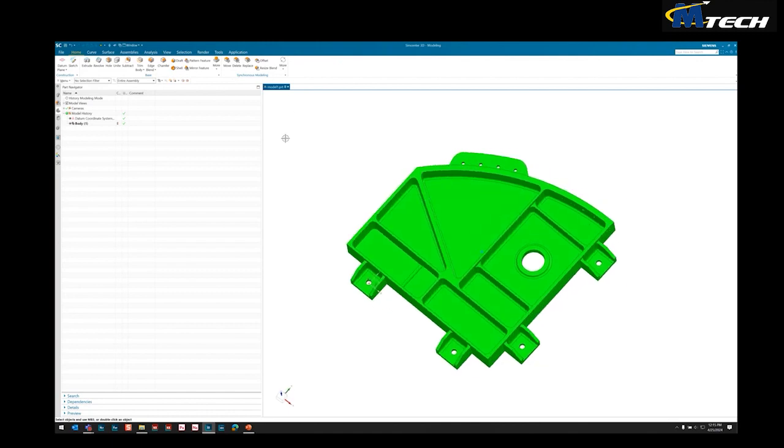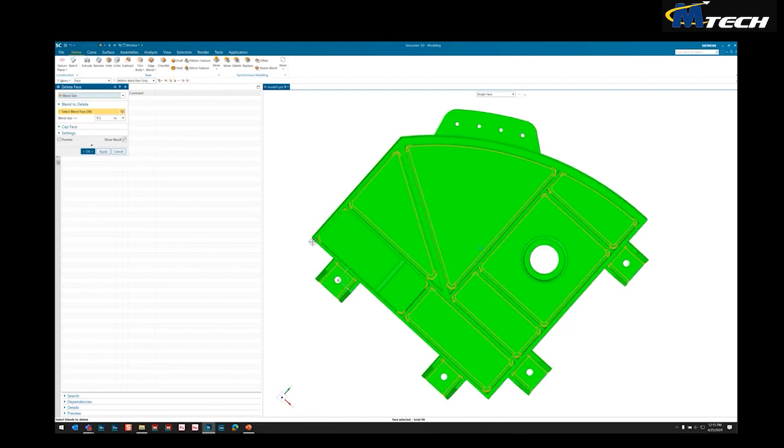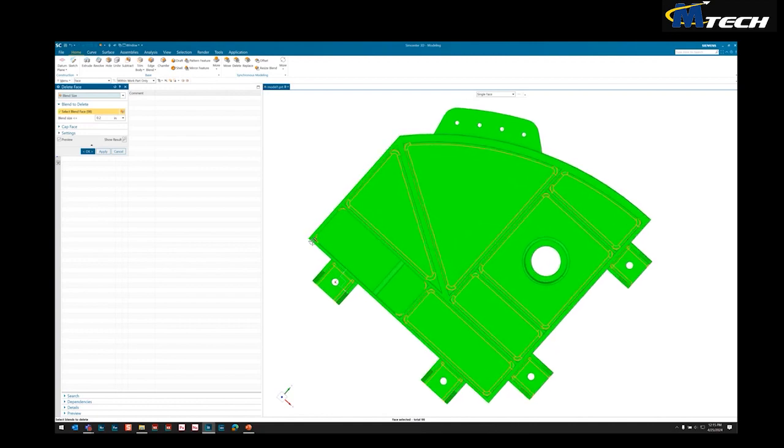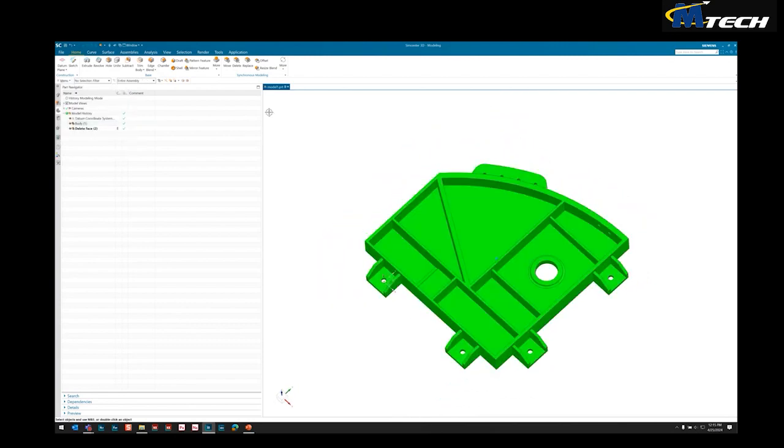And the first thing we're going to do is delete these blends, since we're doing a mid-surface mesh. We can select them quickly by just picking a blend size, and it will pick all the blends that are within our size threshold. You'll see there are a couple here that it doesn't pick, and we want that to be true because we want to have thickness transition areas here. So this is what we want. Hit OK, and our blends are removed.